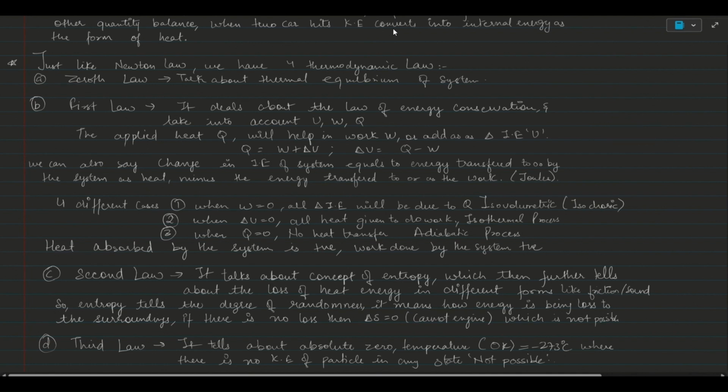Now what's next we are going to do? Let's open the gate of C, and equilibrium is set up between B and C. Now as a final system, all three A, B, C are in equilibrium with each other. Again, A is in equilibrium with C also. Why? Because A is with B, B is with C, then A is with C. I mean, try to understand. That's what the zeroth law tells us, the thermal equilibrium of a system.